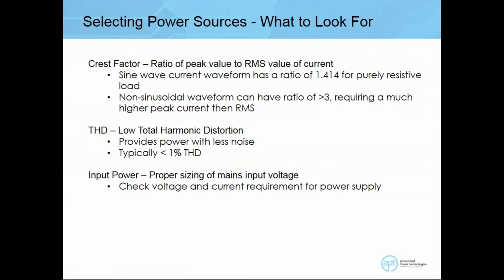THD, total harmonic distortion. Again, we mentioned that switch mode power supplies suffer from high THD. If you're looking for clean power, you want to make sure that THD is as low as possible, preferably less than 1%. Since we're producing a sine wave from these circuits, we want to make sure there are no other components of the 60 hertz sine wave added to the main component at 60 hertz.